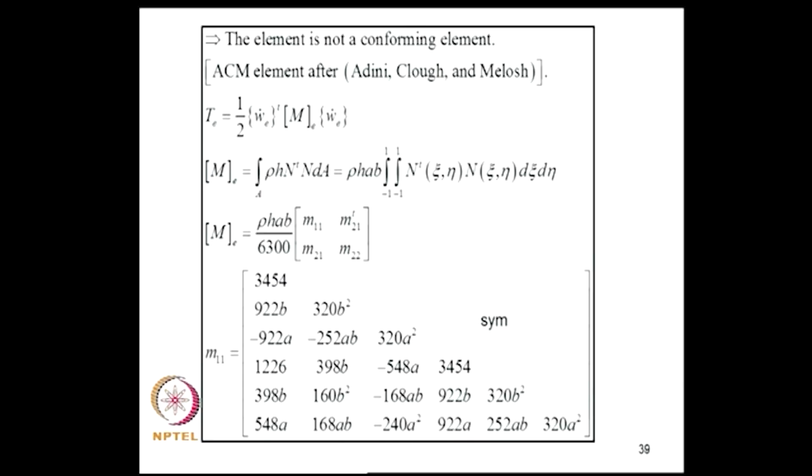So at this juncture we will close this lecture. In the next lecture we will complete this formulation and derive the mass and stiffness matrices, and then examine how to develop a conforming element. One idea would be to use products of beam trial functions in the 2 directions. We have used cubic polynomials for analyzing beams. If you assume that the plate is made up of 2 beams which are orthogonal to each other, then we can utilize products of the shape functions that we use for the beams and develop an element, and let us see how that happens in the next class.